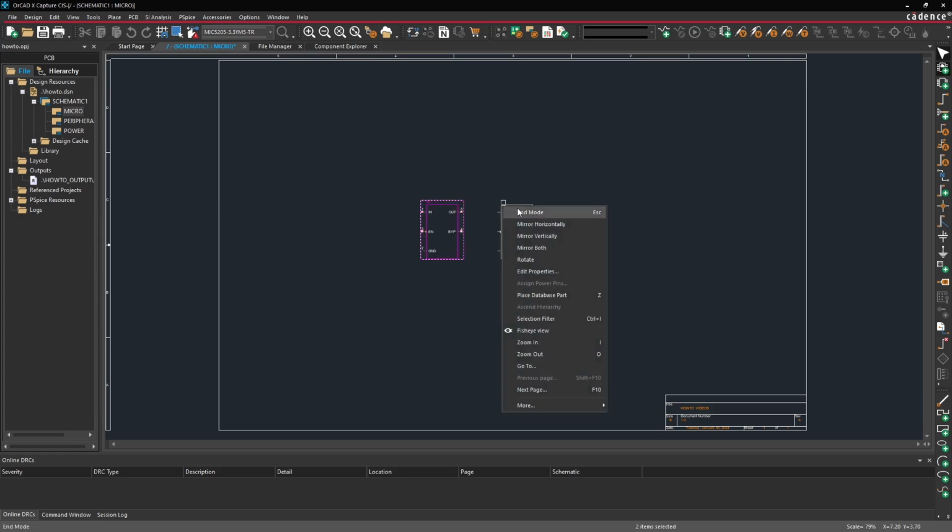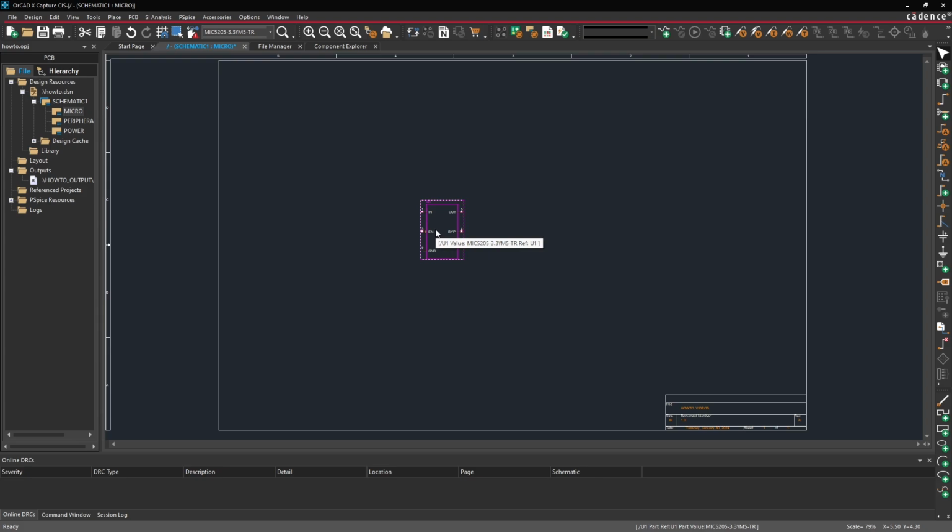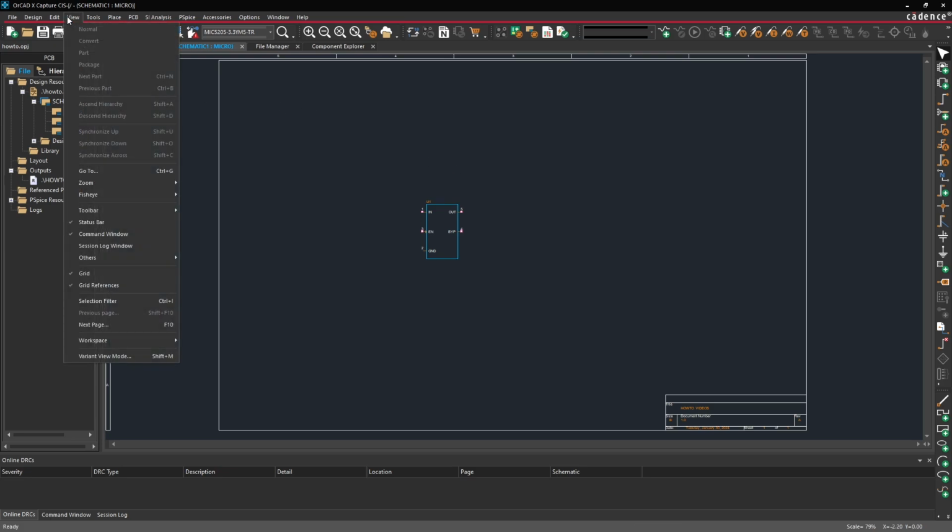What this will do is attach that manufacturing part number to this instance of the part that we've placed and make it so that when we go to export the bill of materials using the LiveBOM, we can see all of that manufacturing information for this component in the LiveBOM. We're not going to go too deep into that in this video, but just to give you a preview, let me save this first and launch the LiveBOM.